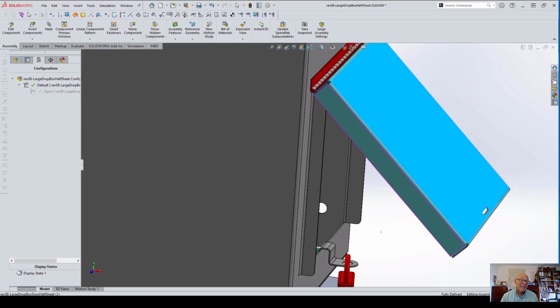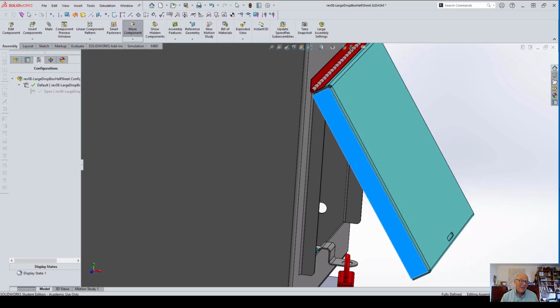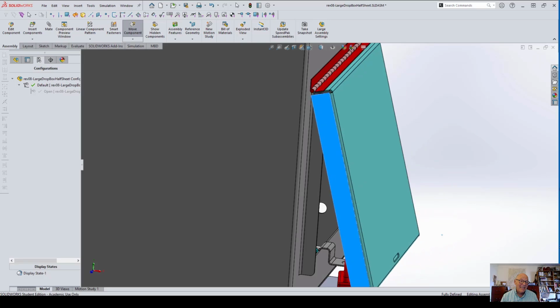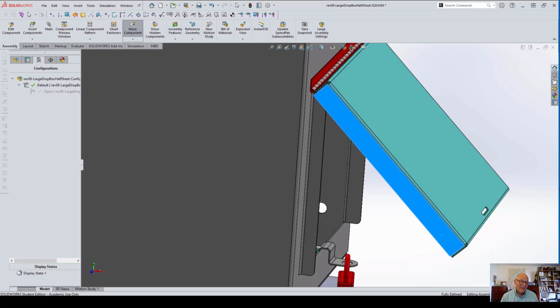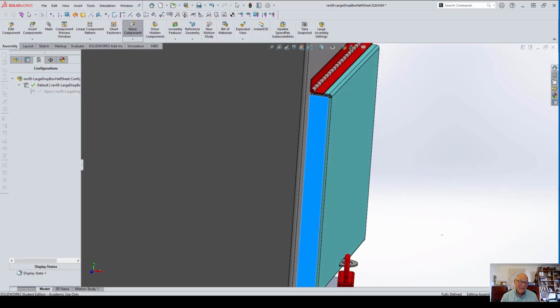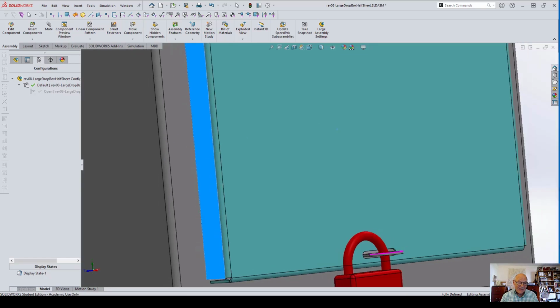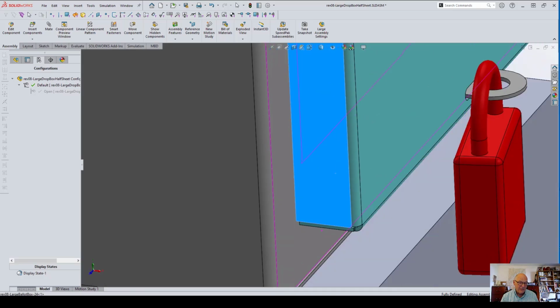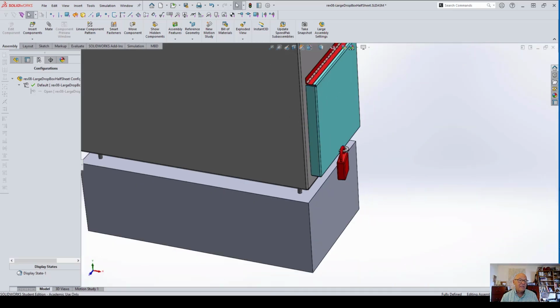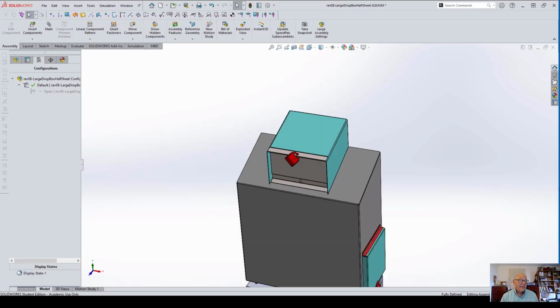And this is when I discovered that if I thought there was going to be a straight corner on that, and I thought I could pull that down across it, it was going to bang into that corner right there. So I had to go in and get some relief on that, and I was able to do that with this. And you can see I could also make sure that the slot was going to line up with that tab that came out. All of these, by the way, are not shown welded. They're just shown as it's folded, so that's why there's still a gap there.